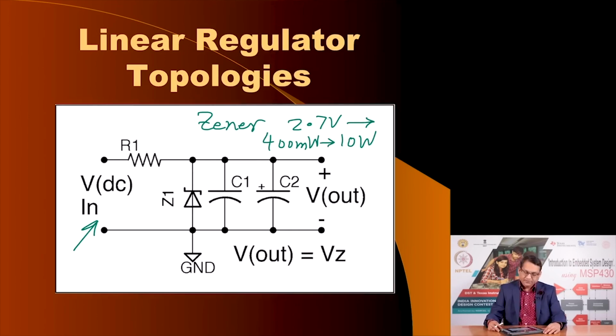and so it could be used to create a power supply system. This is not a very efficient system for various reasons, and it also uses several components. One, you need a series limiting resistor, you need the actual Zener diode, and you need 2 capacitors as I mentioned. C1 would be a ceramic capacitor and C2 would be an electrolytic capacitor.